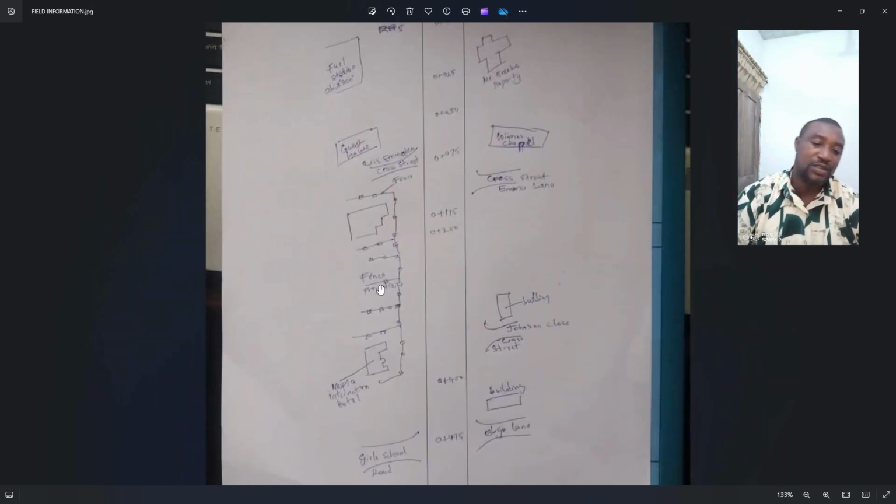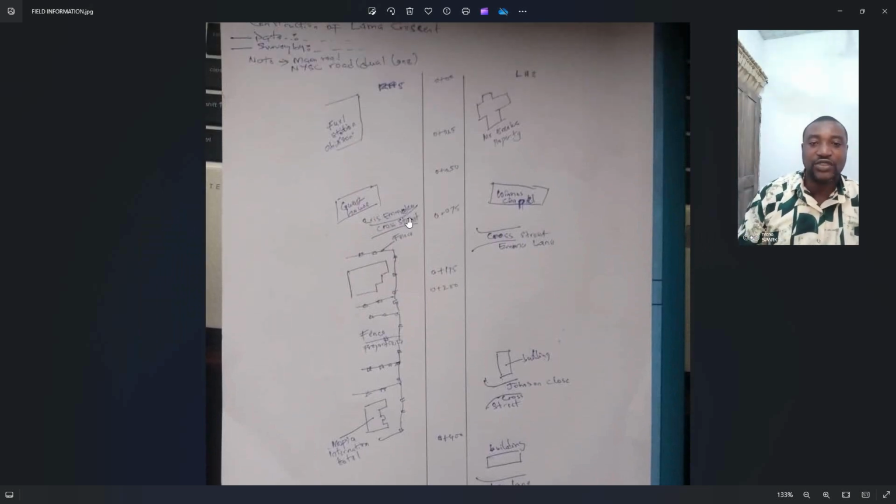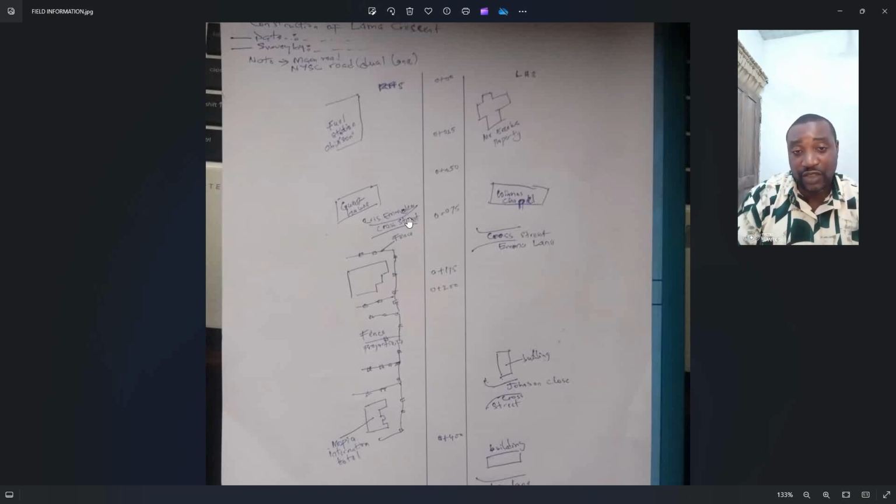Now I think this is quite useful. So when I'm entering information on the design, that will be the next class, I can be able to relate this information when I start to sketch these items that are on the ground before I can bring the center alignment where the road will pass, because who knows if some of these buildings fall into the path where the road will pass through. So one has to be very careful and always have an interest to see whatever the surveyor got.